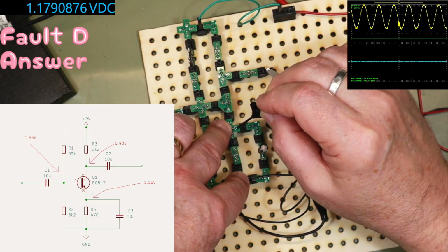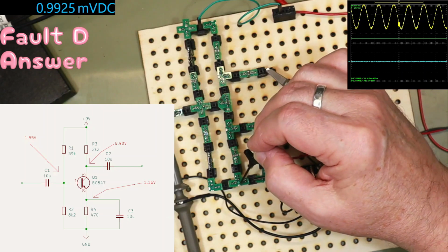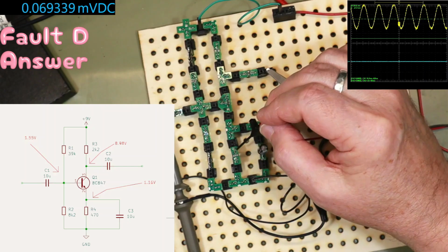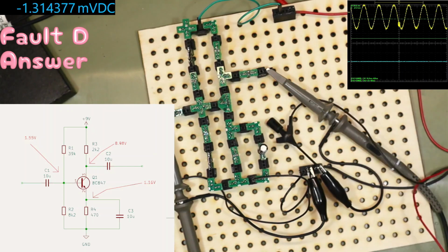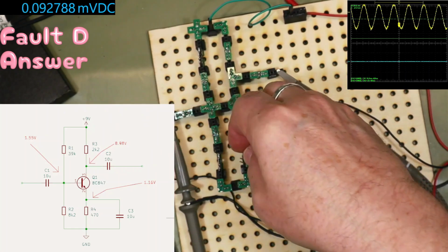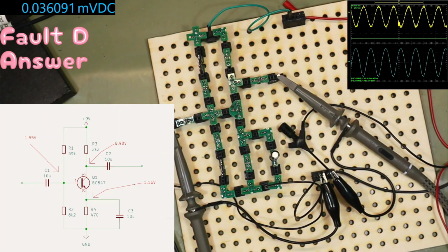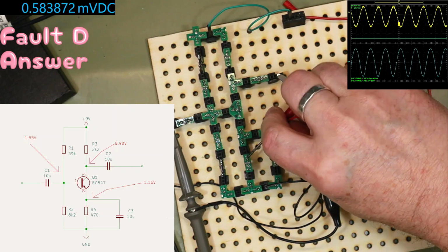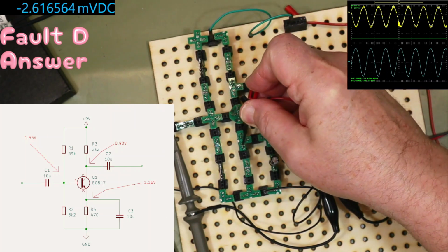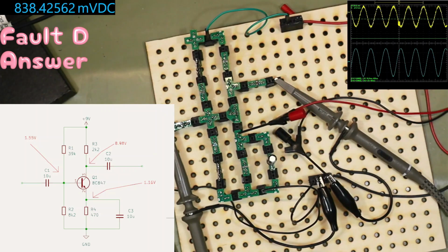You know, again, we can do things with it. It's showing you that this point here is not tied to that point, the ground, in any way, hinting that R4 is open circuit. So again, if I pull it out, put it back in properly, and everything is now hunky-dory. We'll be back to the 0.8. Doesn't want to stay on. Come on. It just doesn't want to stay on this time. There you go. We're back to the sort of 800 millivolts that it's designed to be at.